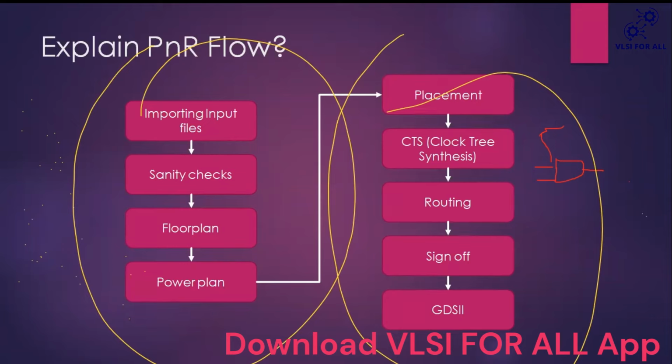After creating the floor plan, the next step is power plan, and most of the time people include power plan in the floor plan stage itself. During power plan we create power stripes and power S routes, meaning special routes, and connect them. From the S routes, power goes to the standard cells.